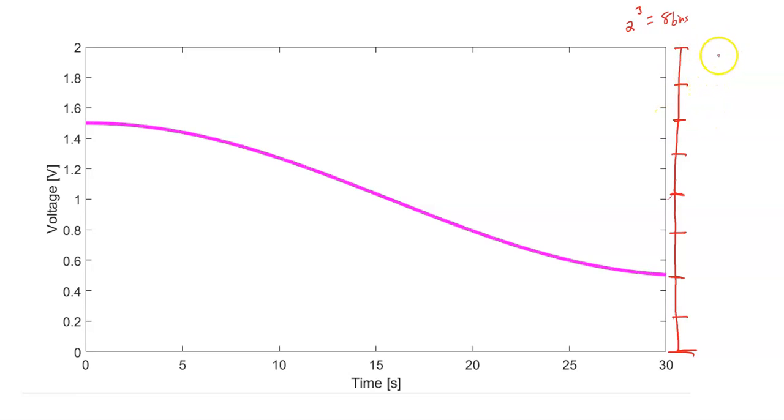And so our second might have a different full-scale range. Let's just say, for argument's sake, it goes from negative 0.5 volts to 2 volts. This wouldn't be typical of an A to D converter, but let's just say it did.